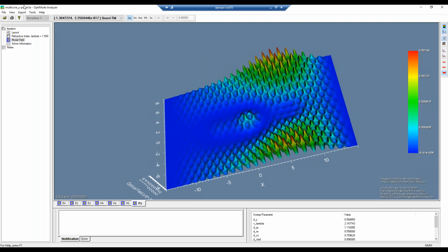Once you calculate the modes, you have some understanding of how mode beating happens and how coupling works. You can calculate the coupling length, and you'd be able to design the structure with the proper lengths of these waveguides. And you could use this structure to couple out polarizations from the center core selectively into either one arm or the other, depending on its polarization.